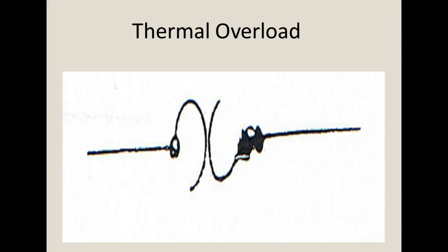So I got double throw, click, click, click, click. See, they're tied together, click, click, click, click. So that's a double throw. And how many poles? 2 poles. Here and here, or here and here. A little confusing, just want to make sure y'all understand that.